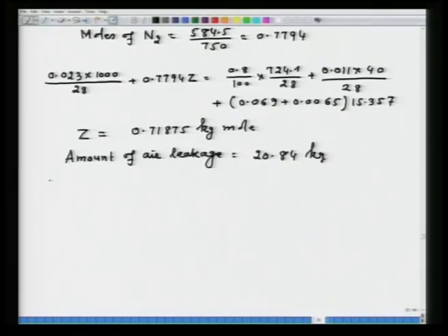Now, you have to find out the fraction of original heating value of coal that is available and so on. So, first of all, you have to find out the gross calorific value, because the calorific value of the coal is not given. So, we will find out gross calorific value on dry basis. The concept of it I had already given to you in the earlier lecture. Now, GCV on dry basis, why I am calculating it is as follows. Coke is given on dry basis, there is no moisture in this. Volume of gas is also given on dry basis, there is no moisture. So, as such we have to calculate gross calorific value on the dry basis.